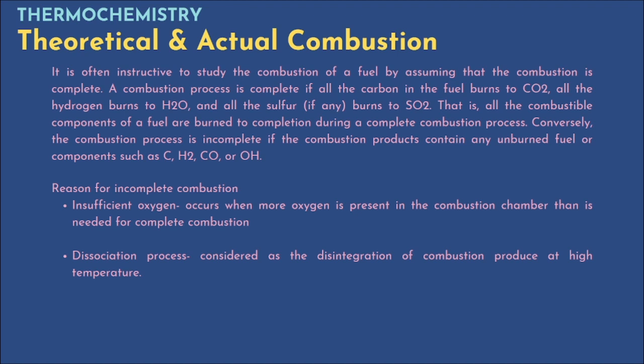Conversely, the combustion process is incomplete if the combustion products contain any unburned fuel or components such as C, H2, CO, or OH. Reasons for incomplete combustion: insufficient oxygen; more oxygen present in the combustion chamber than is needed for complete combustion; and dissociation, the disintegration of combustion products at high temperature.